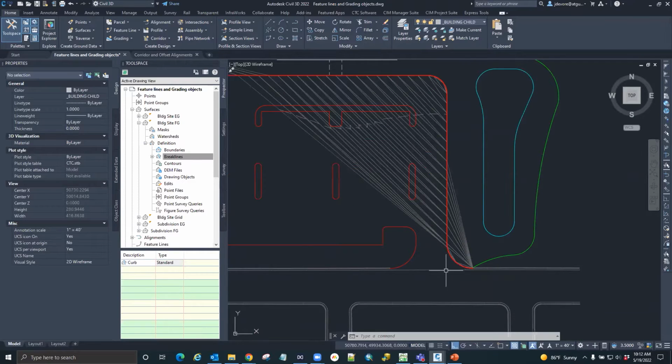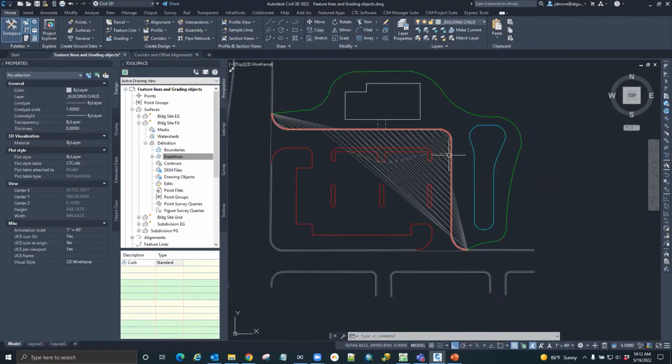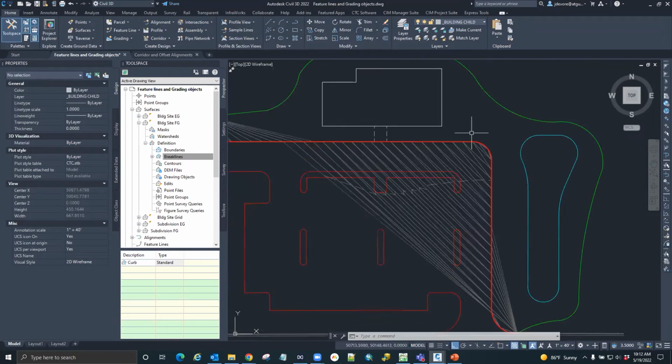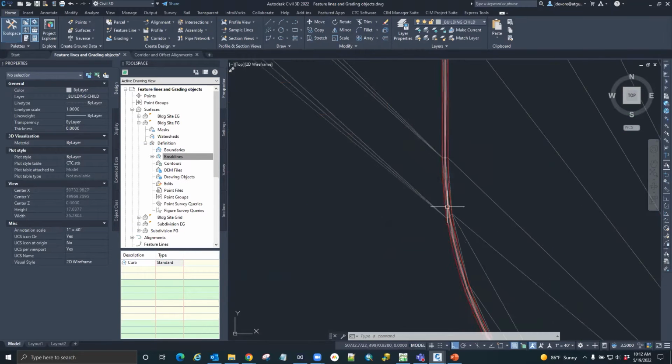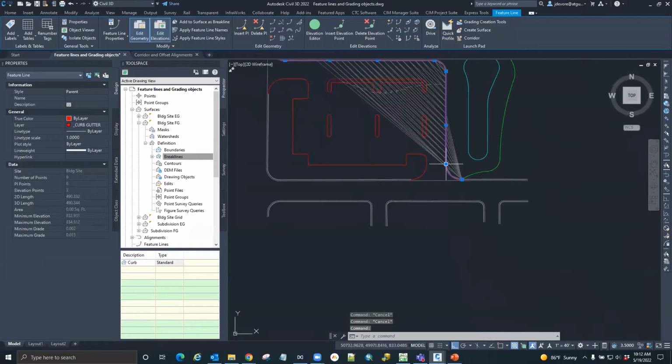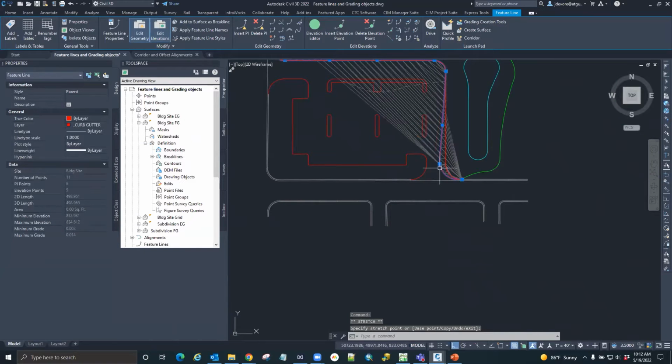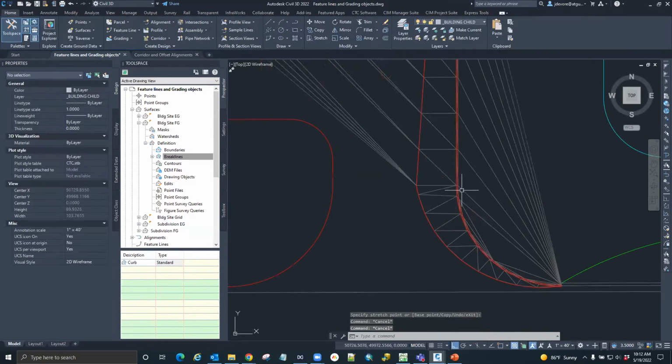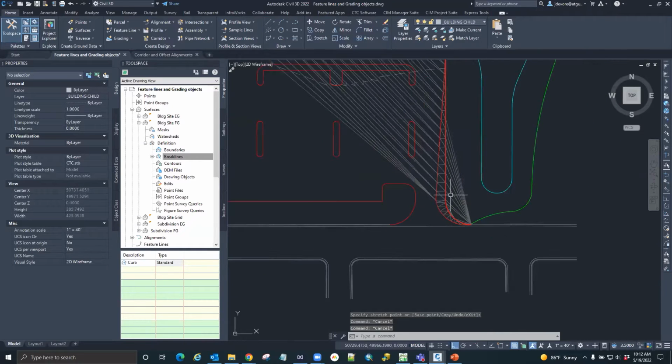So this, at least in my opinion, Felix, is kind of the quick way of getting an idea across. Utilize feature lines to get yourself a quick little surface. Now, one disadvantage I see is these are not dynamically linked. If I had a design change, we never have those in the industry, but if we had to adjust the X and Y there, my stepped offsets don't come with me. So I'm going to have to redo that again.